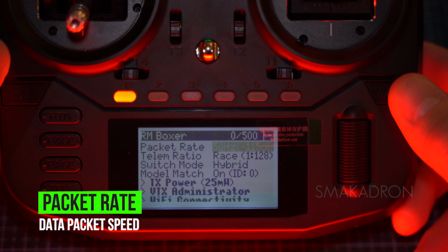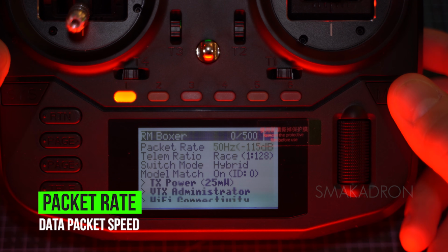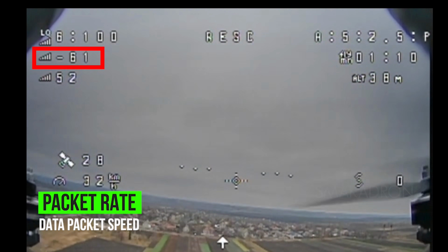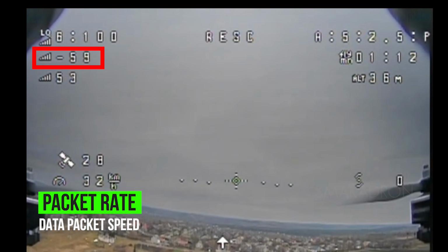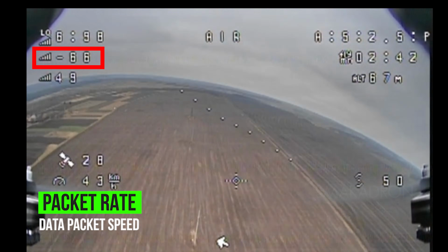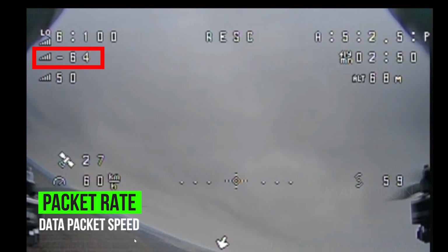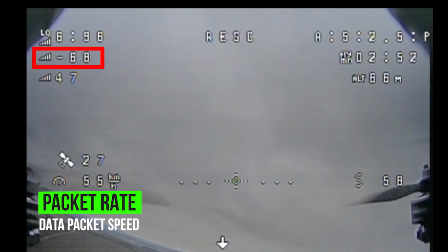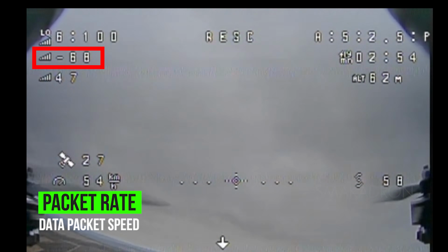Next to it, we see the value -115 dBm, which defines the RSSI sensitivity limit. This value is displayed on the OSD in the goggles. It is the lowest theoretical RSSI value that the radio receiver can distinguish.